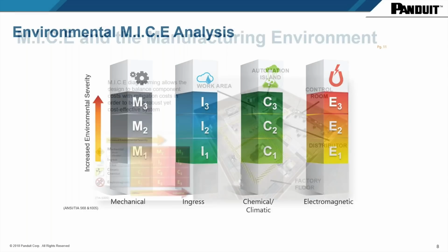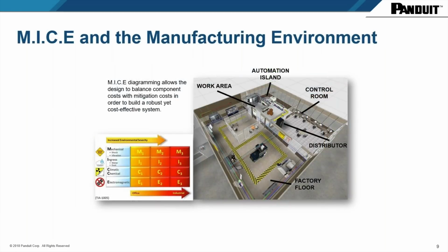So then, if you look at a factory system, you would think that all of these different areas are alike. In fact, they are not. Why it is important to look at a layout in a given factory system and decide where is my extreme environment? Where can I, or do I need to be careful what type of networks, cabling, and connectivity I need to apply? So when you start looking at these areas, you would start with, say, a control room.